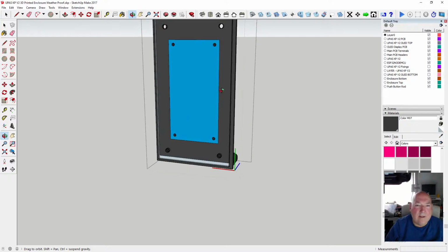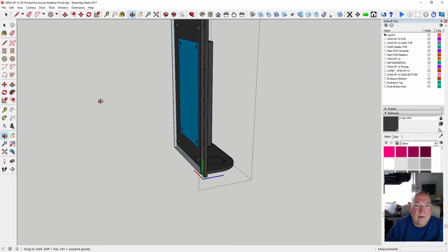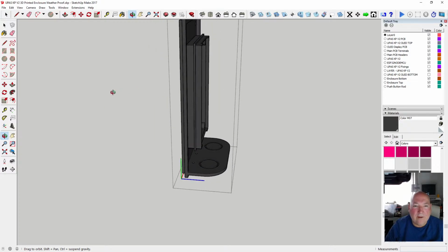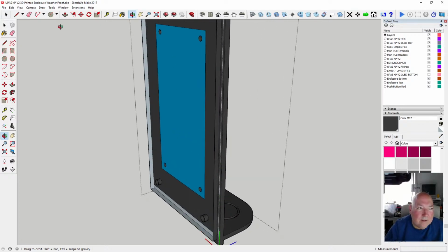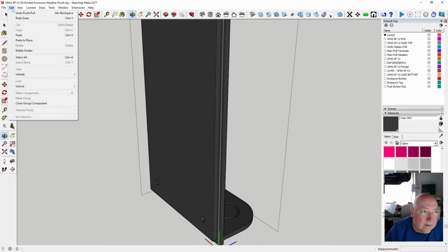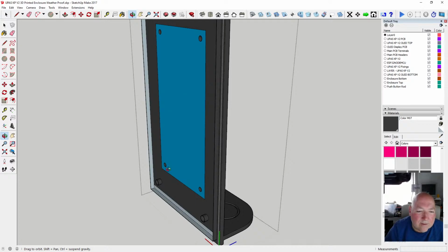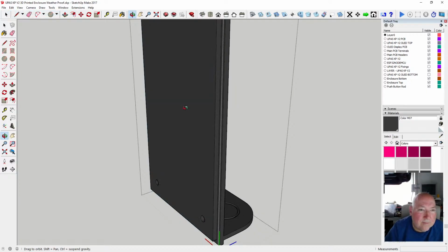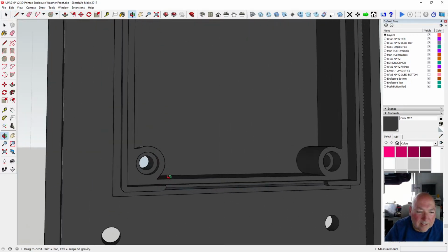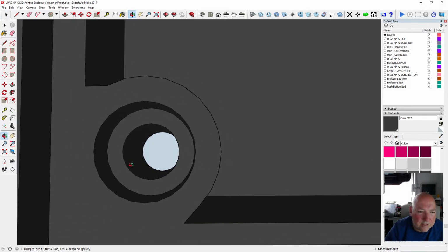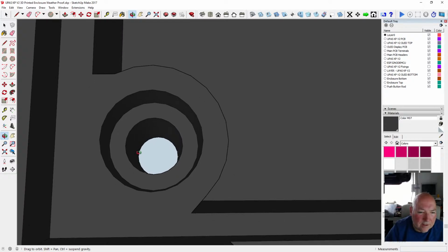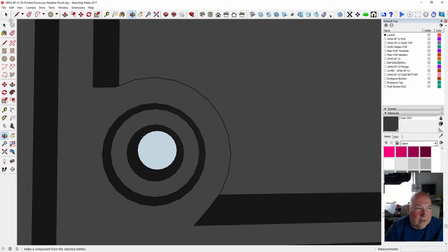So we need to bring the whole thing forward a bit, or make it part of the surface. Yeah, make it part of the surface. So now if we do an undo erase, it's going to put it back. Redo erase. So, oh, we've lost the back. That's fine. So it wasn't what we thought. It's just the inside of the back. We've got 0 thickness. Well, that's no good to us, 0 thickness.